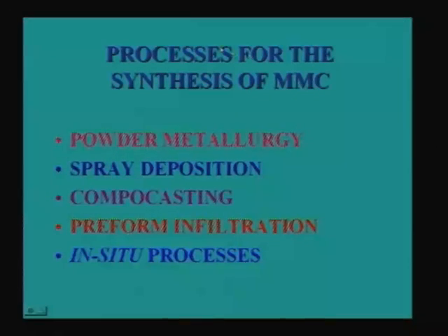In a normal stir casting route, one has to hold the liquid metal for a long period along with the particles, because of which you can have more reaction. So that is why one goes for infiltration, but as I told you, infiltration itself has limitations, and because of which new techniques have come up, which are called in-situ techniques. In in-situ processes, we generate these particles in situ. We will go into detail about this.